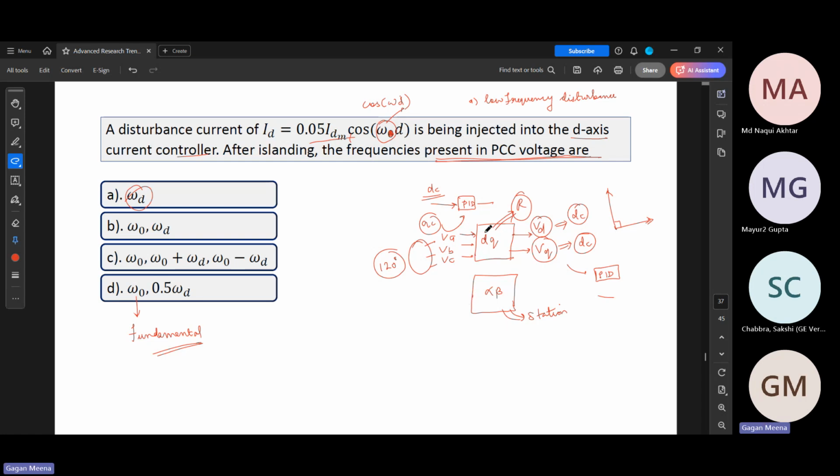We'll see this again in the future, in the 6th or 7th week. Both these we will see again. So when we convert these, if this is current, this will be IA, the current of phase ABC. We convert them into D and Q quantities. So we call it the direct axis current, and this will be the quadrature axis current.